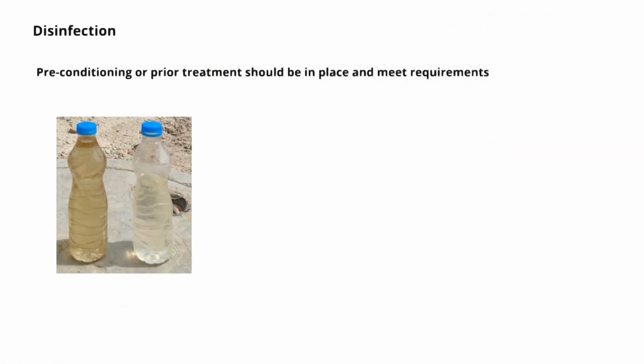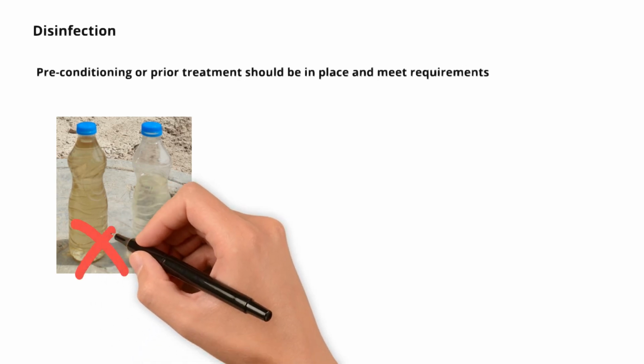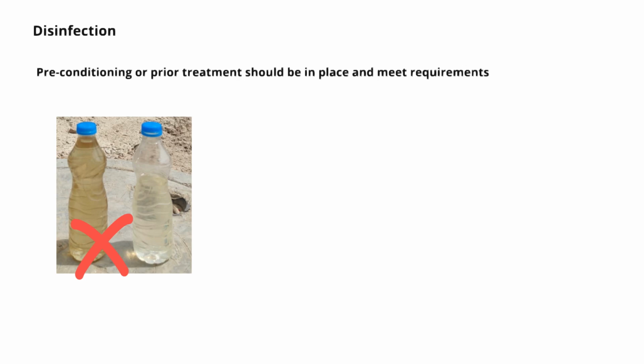This is especially relevant for organic matter, which must be removed as it otherwise harms the efficiency of disinfection processes. For example, chlorine residuals are unstable in high concentrations of organic matter. Consequently, the effluent would require higher doses of chlorine for adequate disinfection. Similarly, UV radiation is inefficient in cases of high turbidity and elevated amounts of total suspended solids in the effluent.